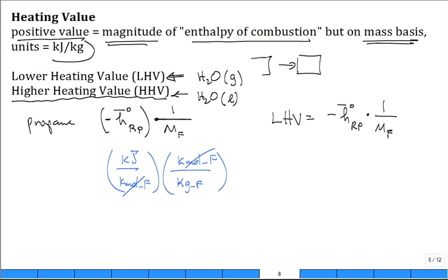Think about it in two stages. This H2O out in the vapor or gas state, and now it's H2O out in the liquid state. Okay, you have to have a heat transfer into this zone or chamber or control volume, true? And it's going to be removing heat, Q remove, per molar flow rate of the H2O. Or, let me ask another question, the heat removed per mass of the H2O.